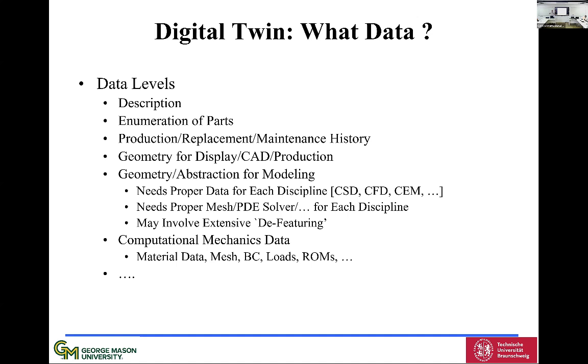I just do a simple line approximation, potential flow. But if I want to go 3D Navier-Stokes, I need to have very detailed 3D wings. So the important part of this is that this needs the proper data preparation, the proper meshing, because that depends on the PDE that you're solving and the type of physics. And then it may involve extensive defeaturing, because for a fluid dynamics model, you don't want every screw and every little detail that is inside the real object.